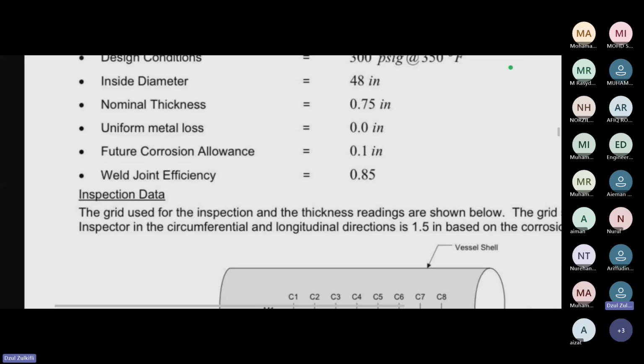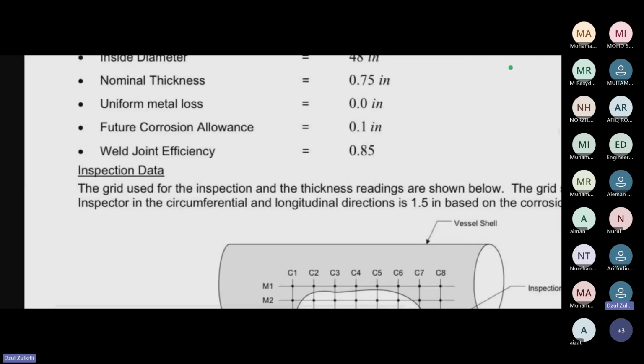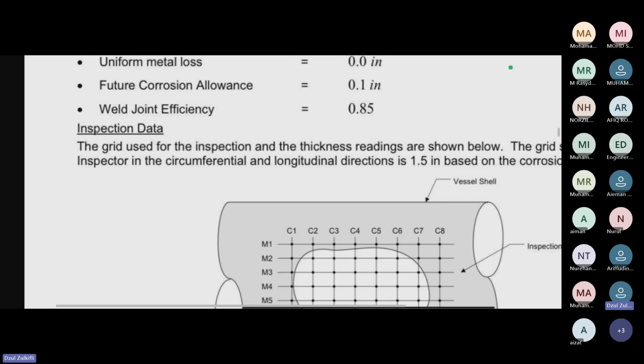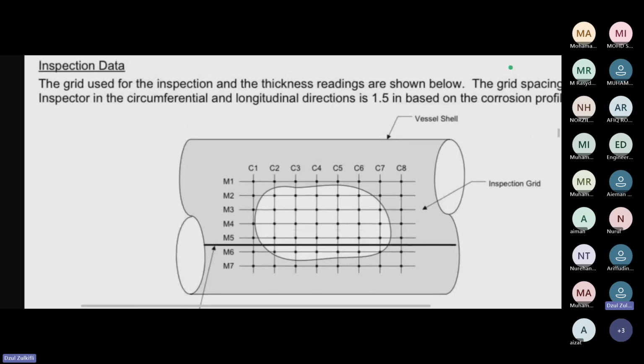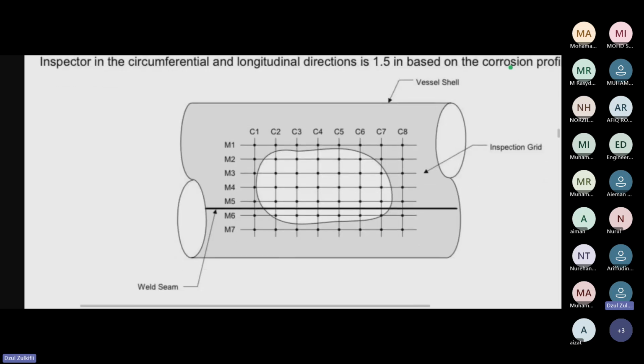Okay? And then weld joint efficiency. Weld joint efficiency is just a number that will be used in your PR over SE calculation later, for design. Okay. FFS, like I said, requires inspection data and very detailed one. You need a grid, right, with proper thickness taken. All the engineering calculation and design I mentioned earlier does not need proper thickness like this. So this is pretty intensive. So make sure you really know, if you want to do FFS, you really need FFS. Okay.